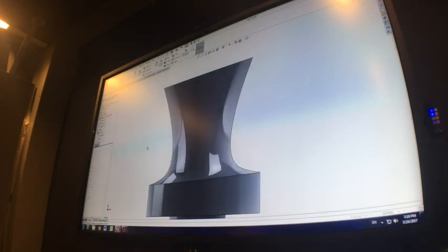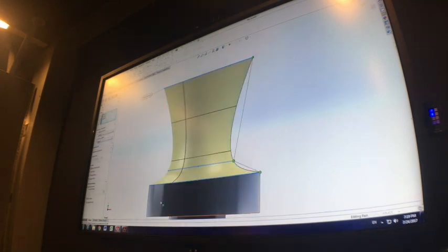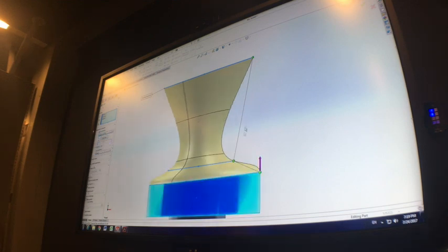We still want that curve, but we want it to be tangent at the bottom here. So start constraint, which is at the bottom. When I press that drop down, you see there's some options, including tangency to face. And that makes it with a nice curve here at the bottom. Okay, so that's a smooth loft around that face and that area. At the end constraint, because there's no other surface there to be tangent with, we don't have that option.